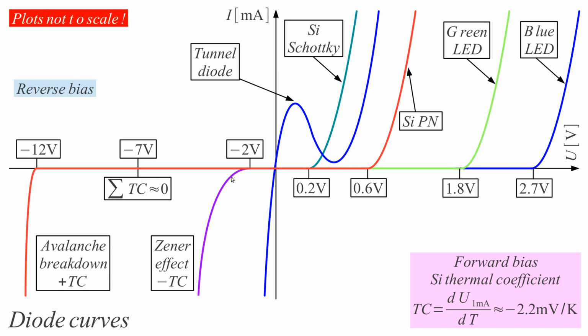This is also a tunnel diode, and further increasing the doping, we get the real tunnel diode that has a very high conductivity already at 0 volts bias. The curve in between this one and this one, but I cannot draw everything here, is the so-called back diode. The back diode has this big drop down, but still it has better conductivity in the reverse bias rather than in the forward bias.